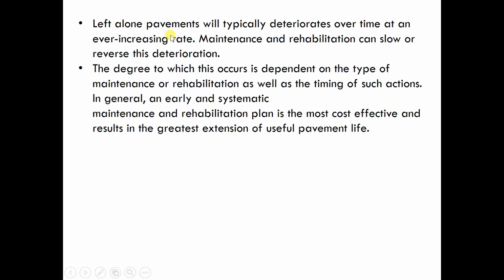So left alone, pavements will typically deteriorate over time at an ever increasing rate. Maintenance and rehabilitation can slow or reverse this deterioration. The degree to which this occurs is dependent on the type of maintenance or rehabilitation, as well as the timing of such action. In general, an early and systematic maintenance and rehabilitation plan is the most cost-effective and results in the greatest extension of useful pavement life. So maintenance is actually very important